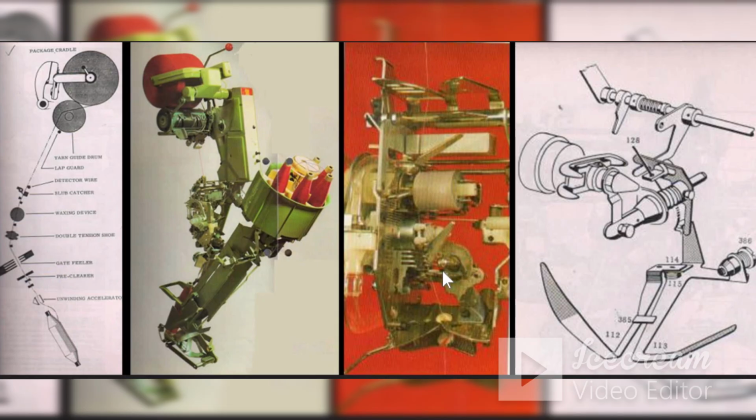If yarn is absent here in the gate filler, that is, if the spindle stops and yarn is absent here, then the gate will penetrate fully. If the gate penetrates fully, that indicates that the ring frame bobbin is exhausted.